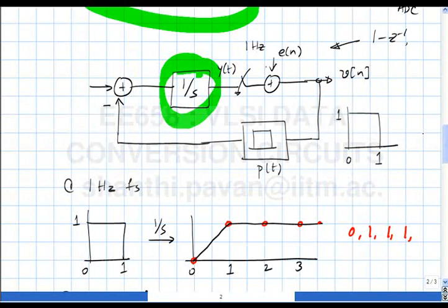So this is exactly frequency scaling, which is the same as time scaling, correct? In a sampled data network, where there is sampling going on, everything with dimensions of time, so all time constants, scale by the same factor, which means that even the sampling time scales by the same factor.